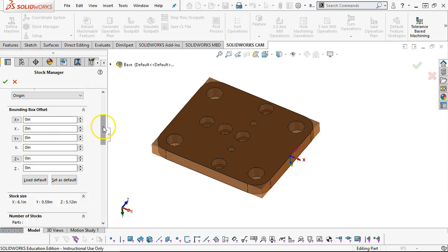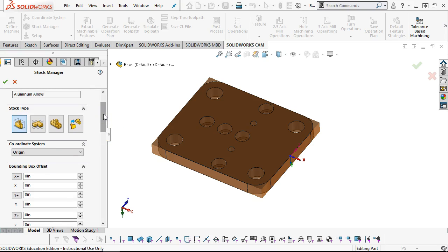I prefer to create a solid body, or my actual preference, if this was a next level up, would be to pull this into an assembly. So in the assembly version, if I was running multiple work offsets, multiple vices, I would have that capability to jump from coordinate system to coordinate system. And on my CamWorks license, I will actually pull this part in, and that was being able to populate multiple vices, but then at the other side of it is I'm not making any changes.